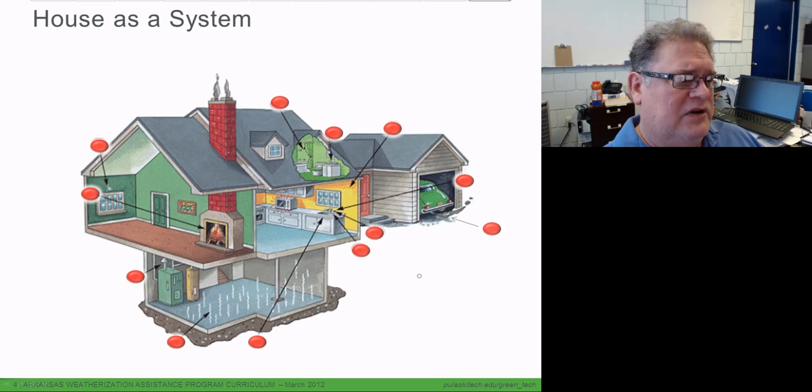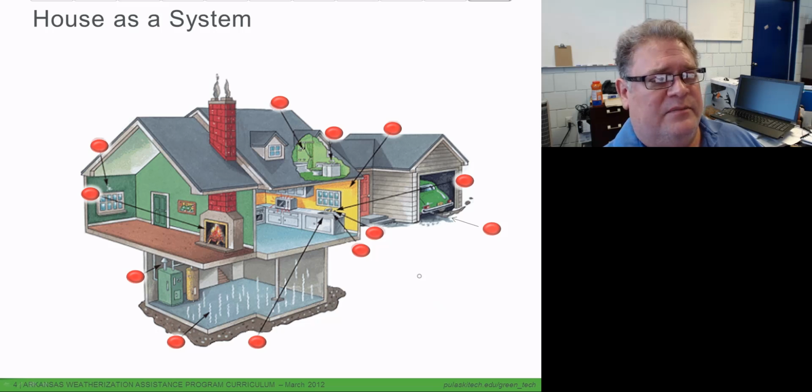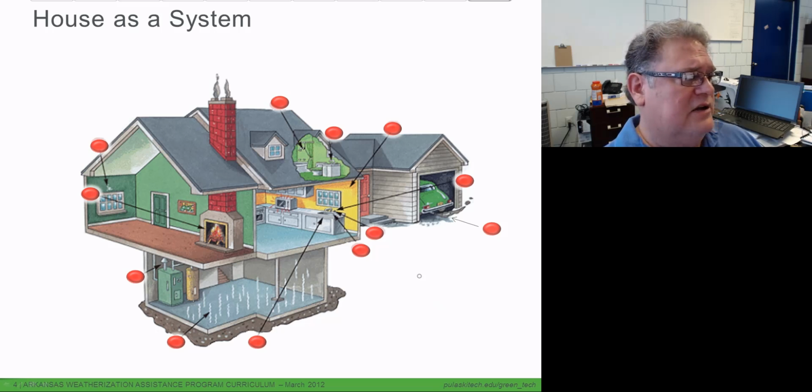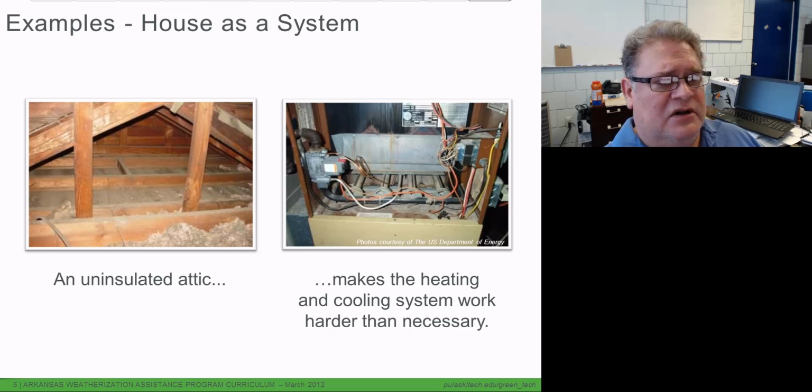But something that we'll talk about a little bit later is that a fireplace is a net cooling appliance, even though we don't want it to be. We want to get some heat, but the problem is it uses so much air for combustion. If it gets that air from inside the home, then it's pulling it through the walls and pulling in cold air from outside. So only the room that the fireplace is in is going to be nice and cozy. All the other rooms are going to be cold.